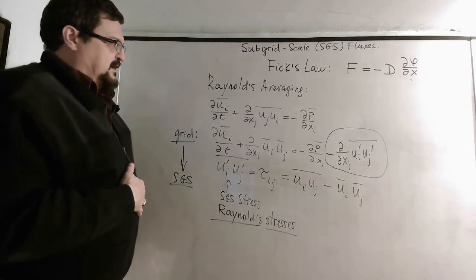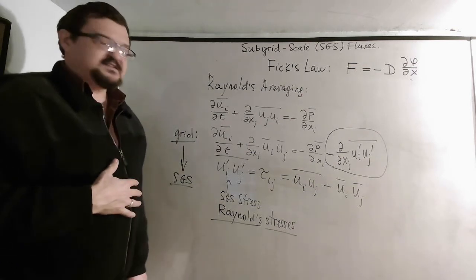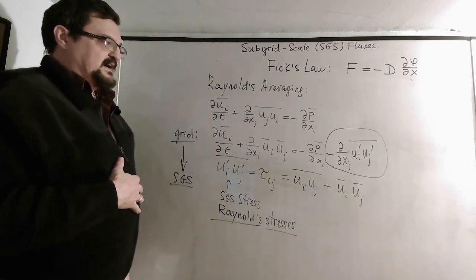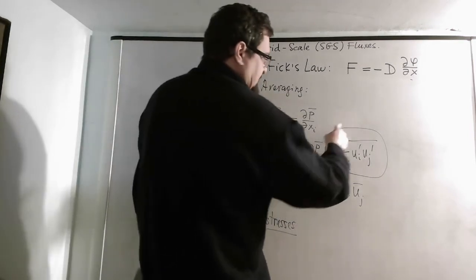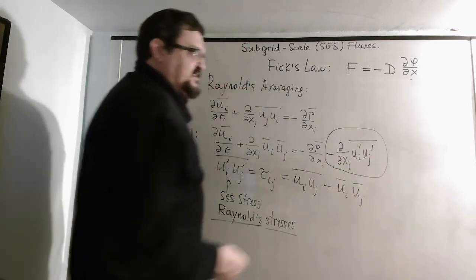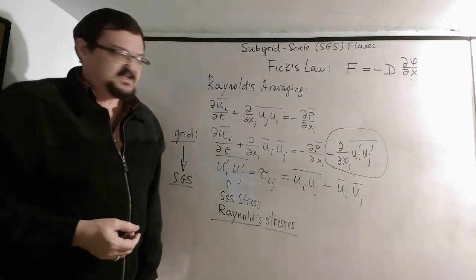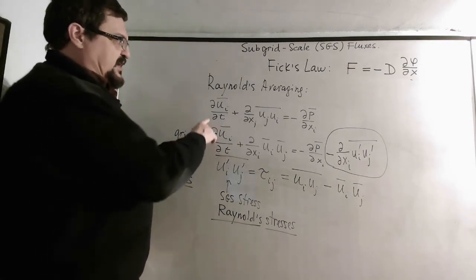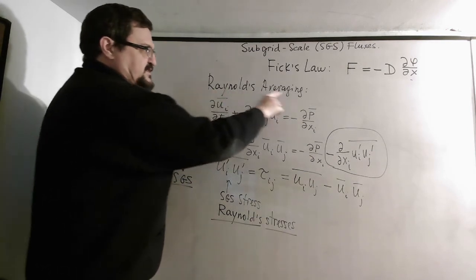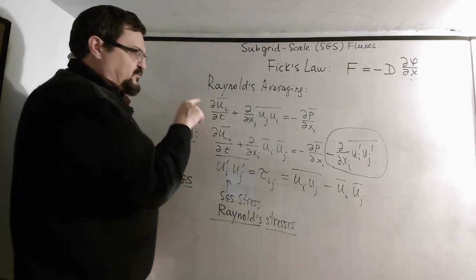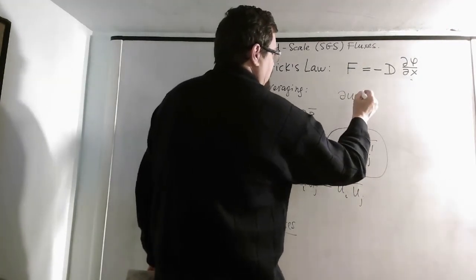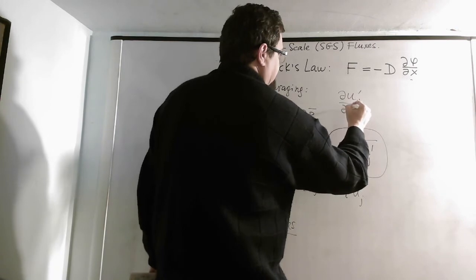So one of the methods that is probably one of the most popular is that you can write equations for the Reynolds stresses themselves. How to do that? Well, you have your original equation without these bars, and then you have equations for the bars. If you subtract one equation from another, you will have an equation for the rate of change of perturbation with time.